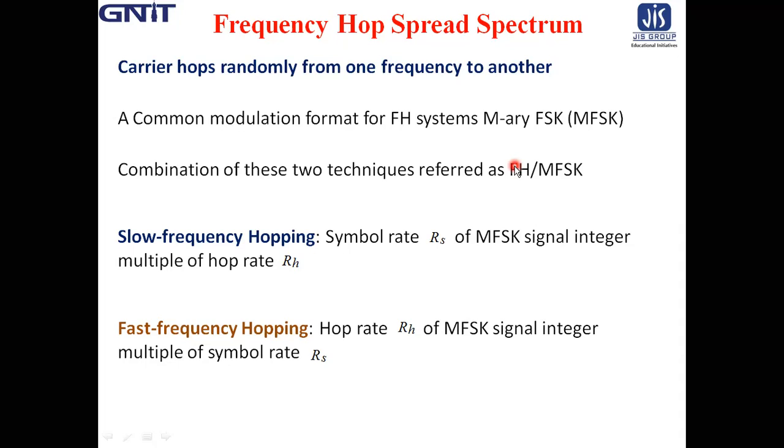The processing gain can be made larger by employing a PN sequence with narrow chip duration, which permits a greater transmission bandwidth and more chips per bit.